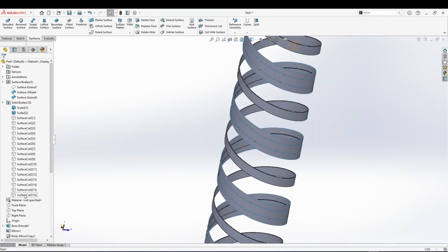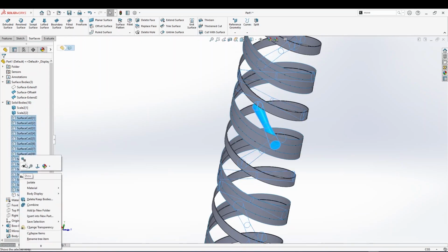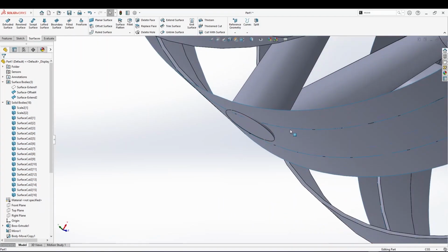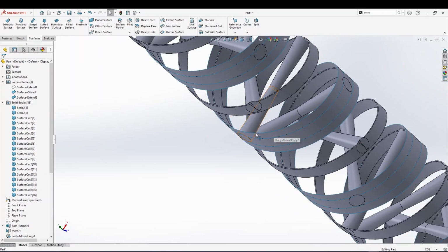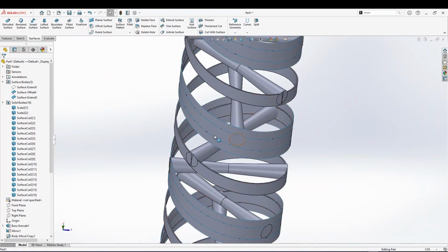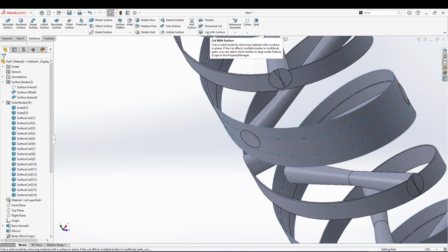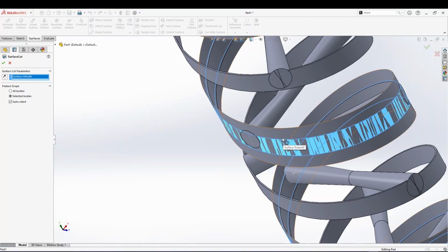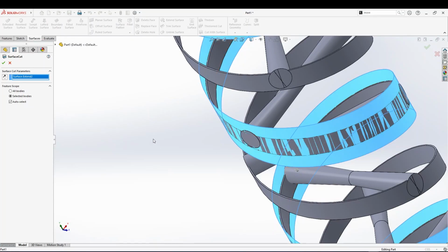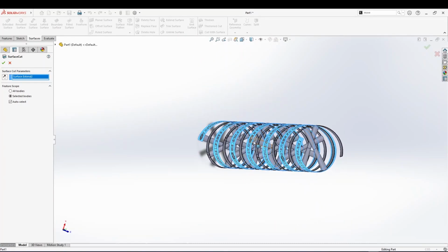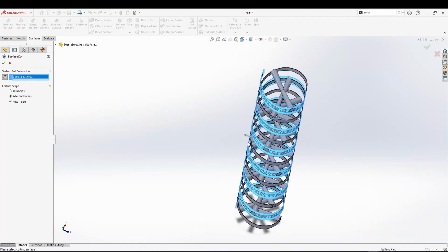And again, now we bring up all of our bars here, make them visible, and now they are ready to be cut. All this material is ready to be cut, because now this stripe completely intersects all the solid bodies, so we will not have any problems. Cut with surface cut parameters here, surface offset, like here, surface extend, and we need to find this arrow. Where is it? Okay, it's here. Just press on it. We want to cut everything outward. Yeah, so let's do it.